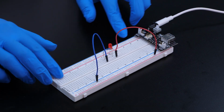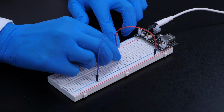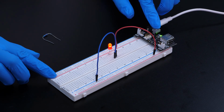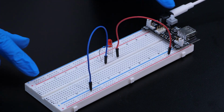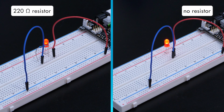If we remove the resistor from the circuit and run current straight to the LED, the lamp shines brighter. This is because more current is allowed to flow through the LED. However, the full current could damage the LED, so we will not keep the power on for long. Next, we place the 220 ohm resistor back into the circuit. The LED does not shine as brightly, but it is in less danger of overloading.